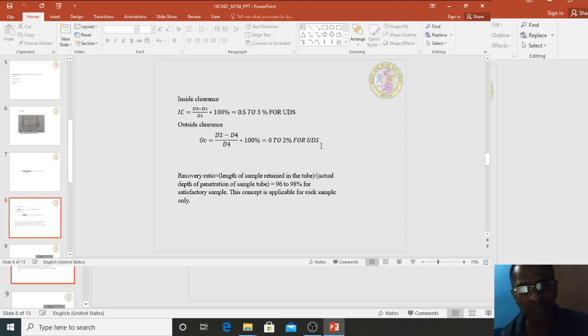In case of rock, we are using what is called RQD. RQD stands for rock quality designation. That means we are using a drilling bit and core catchers for collecting the cores. When we start collecting the core from the ground, we won't get a full length of the core. We will get bit lengths. Some cracks will be there because of faults, fissures, joints, etc. And any sample which is greater than 10 centimeter, we have to add it.